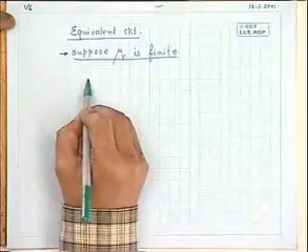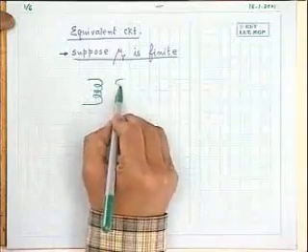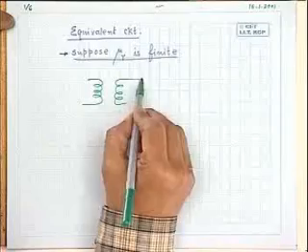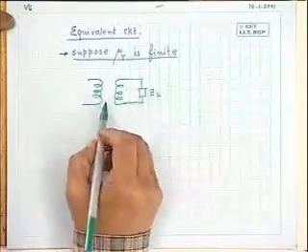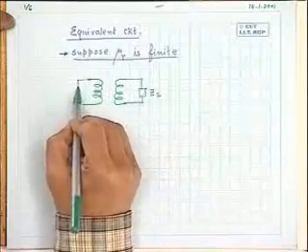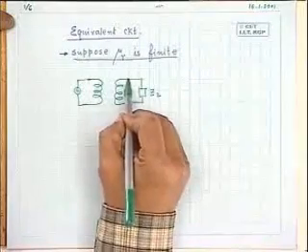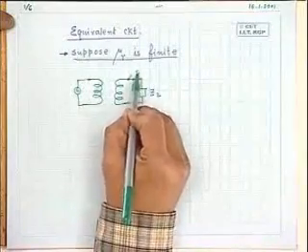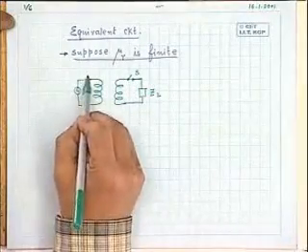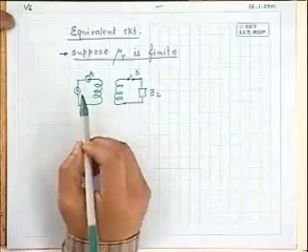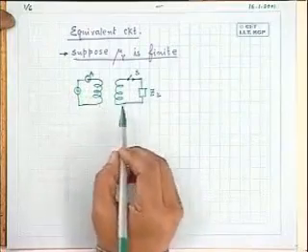And if you remember, we did it like this. Suppose this is a practical transformer, and I will go very quickly. This is the Z2 secondary load, and if you apply a voltage here, when the switch is open, it is under no load condition and the secondary is not carrying any current. If you connect an ammeter here, we have seen that it will draw some current to establish the flux. And this is a practical transformer.